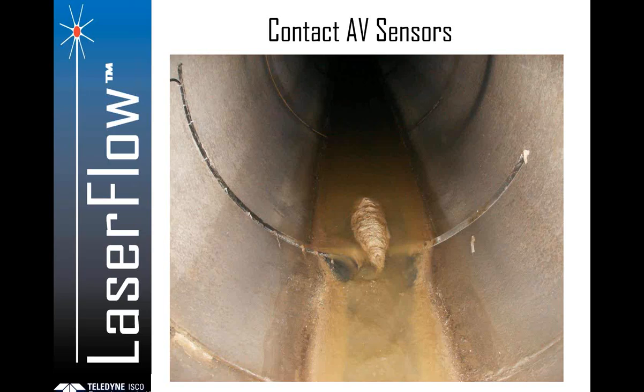So if you've captured a number of days or weeks worth of good data with a clean sensor using the area velocity sensors, we can basically superimpose those graphs on top of each other, and it will set the slope and roughness coefficients for you. And then from then on out, when the sensor becomes covered up, it'll use those variables to calculate flow based on the Manning equation.